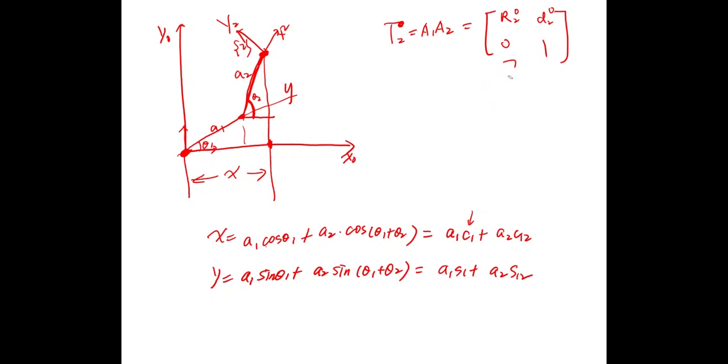So that is equivalent. Again, I want to emphasize that for the DH convention, we use 4 parameters. The first step is to find the 4 parameters for each step. Step 2 is to plug these 4 parameters into all the Ai.